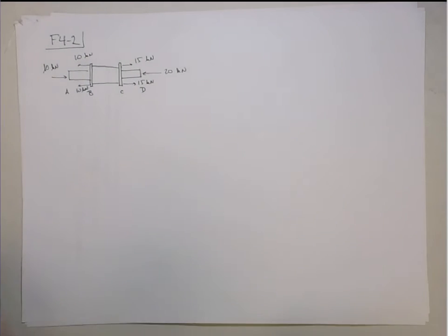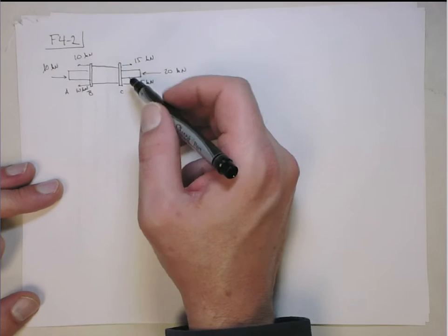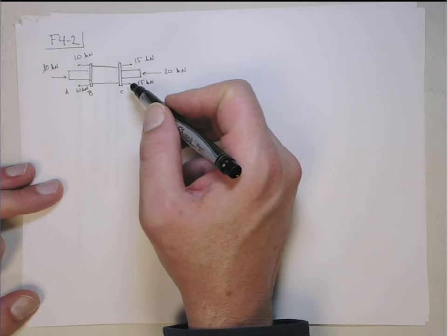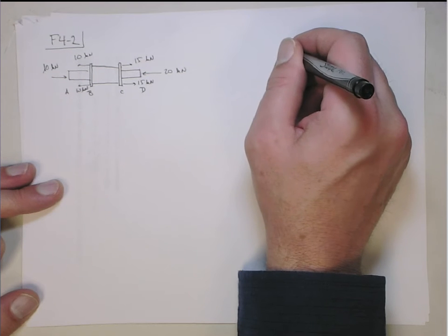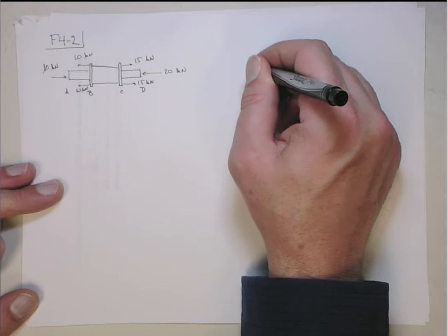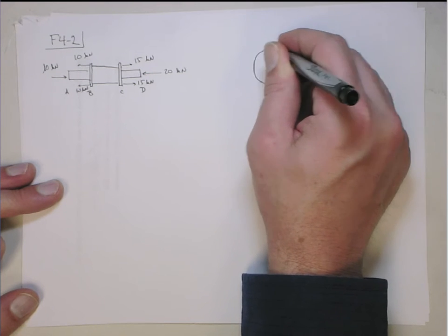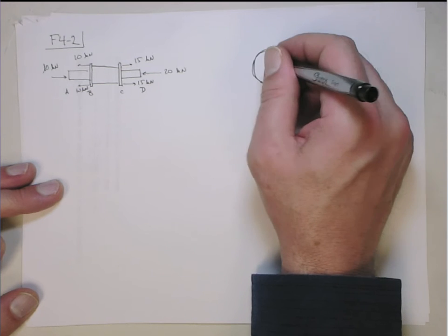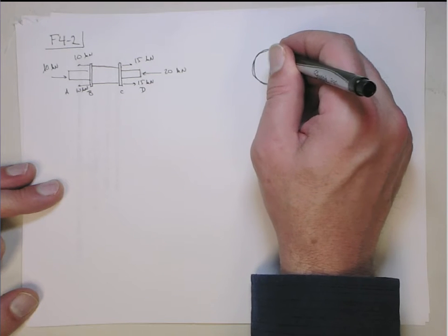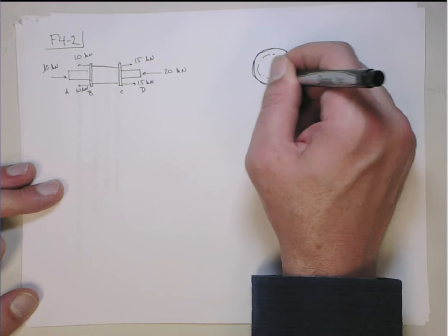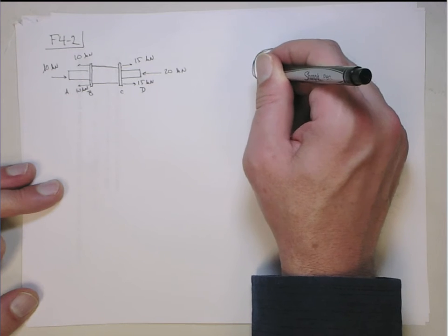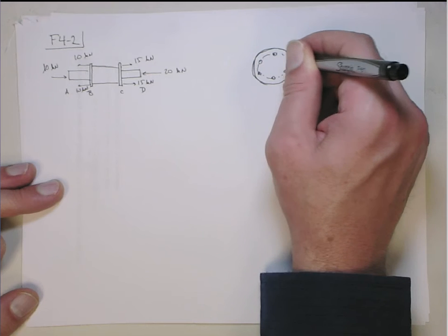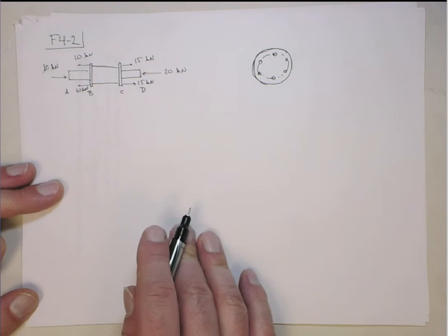Okay, let me just mention one thing real quick. When they draw these, they have these 15 kilonewton forces on the top and the bottom. Just to be clear, typically for engineering structures, the way this is actually done is as follows. You usually have what's called a bolt circle, okay? And usually you have these flanges, and you'll have a circular pattern of bolts around the flange, okay?